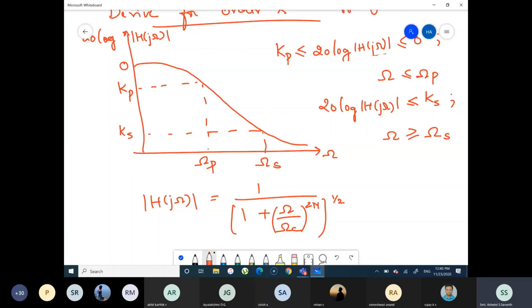So what we have discussed so far is once you know the order of the filter, that is you know what n is, then you can go on to find the poles of the filter, you know the expression for that, and just consider only the left half poles and then write down the transfer function, isn't it? And that too, this we know for a normalized filter. Normalized low pass filter. What is a normalized filter? Wherein you have made omega c equal to 1 radian per second.